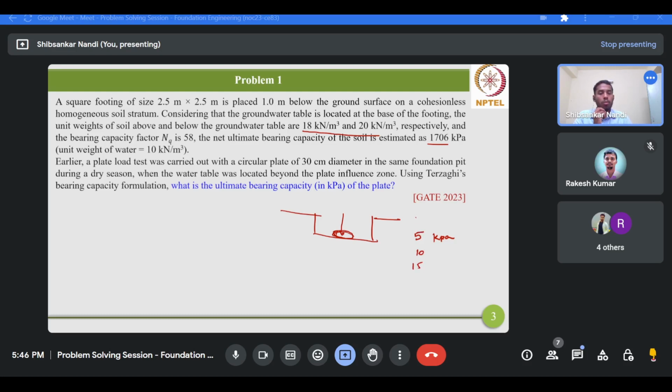So first you start from 0, then 0 to 5, this is one cycle. Then you unload the plate, then again you apply 0, 5, 10, and then again reload 0, 5, 10, 15. So in this fashion, this is called cyclic, and another is monotonic. Okay, where you are continuously increasing the load 0, 5, 10, 15. So there is no unloading and reloading.